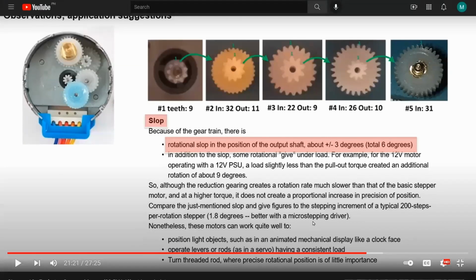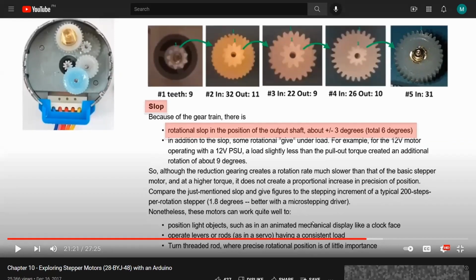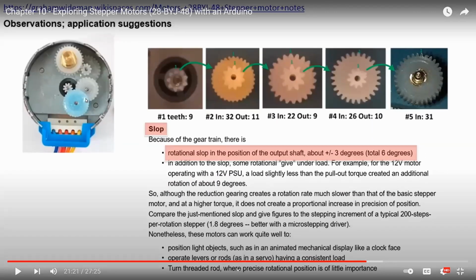So, and this explains the steps of how to do this. There. So you can do finer adjustments with this, and you can design your own gear, and there are several more expensive motors with finer resolutions, but essentially they act the same. This moves in 45 degree steps. There are several gears that will do the gear reduction, and this will rotate in a very fine step.